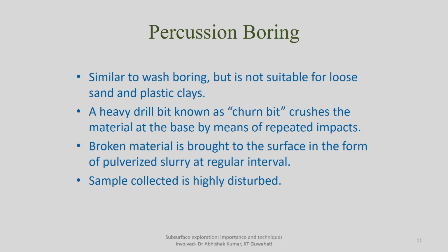Then you have percussion boring, as I mentioned earlier also. Wash boring you can use in soil where the water exerted by the pump is sufficient to loosen the soil, mix it and bring it onto the surface. But it may not be applicable for any kind of medium, particularly gravels and rocks. In that case you have to go for percussion boring, where the way of bringing the material onto the surface remains the same. Here also in percussion boring you will mix up the material with water, and then you will collect it at regular intervals by means of some bucket or barrel from the depth of the borehole onto the surface. So this is similar to wash boring, but it is not suitable for loose and plastic material.